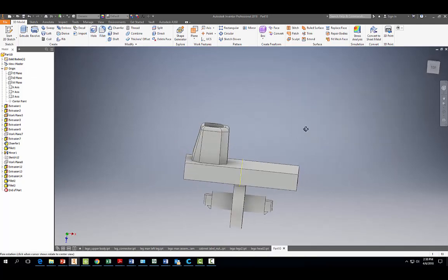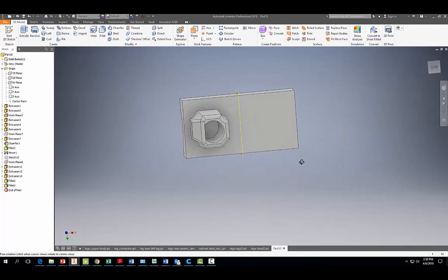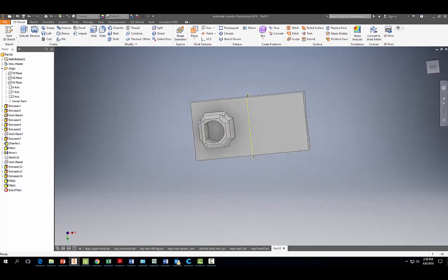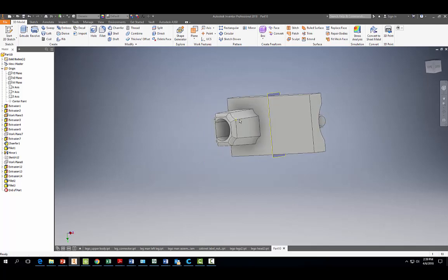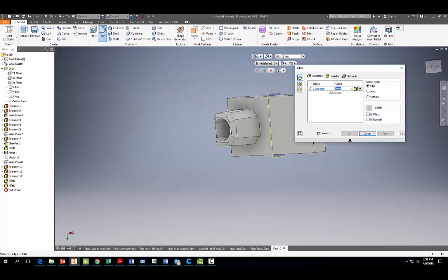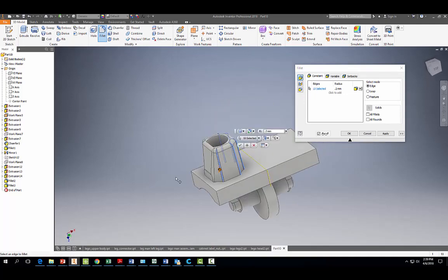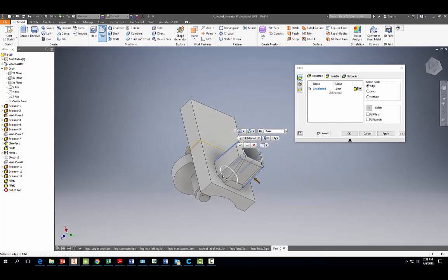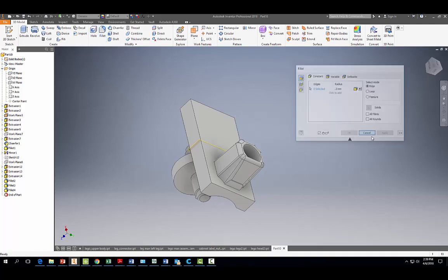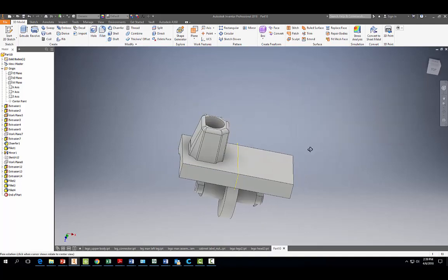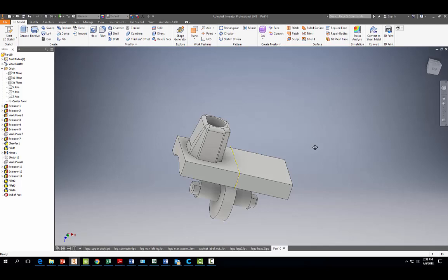And now we're going to throw some smaller fillets, because if you look at the Lego Man piece, none of these are really just sharp, well-defined edges. They're kind of all smooth, even on a micro scale. So we're going to do these about 0.2. Okay, and hit apply. And there you go. Now we just need to mirror it once again.